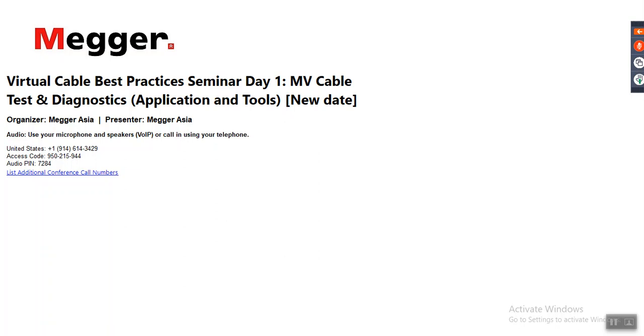Moving to the second question from Fajar, he is asking which parameter we must focus on for tan delta on cable power. The answer is based on the tan delta evaluation graph, typically recommended VLF TD above 4 times 10 to the minus 3, and VLF delta TD greater than 5.